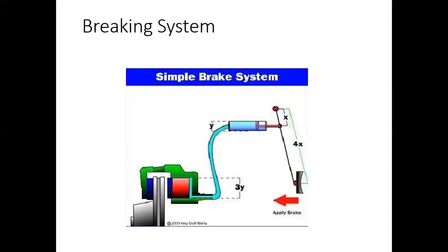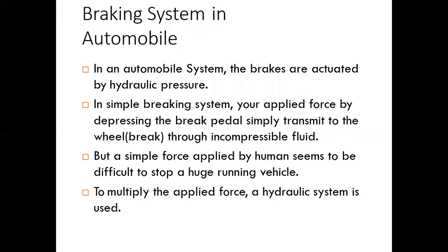So this is the braking system. In a simple brake system, if we hit the pedal, it will produce the braking at the tire. In an automobile braking system, the brakes are actuated by hydraulic pressure. In a simple braking system, you apply force by depressing the brake pedal, simply transmitting it to the wheel through incompressible fluid, but the simple force applied by a human seems insufficient to stop huge running vehicles. To multiply the applied force, a hydraulic system is used.